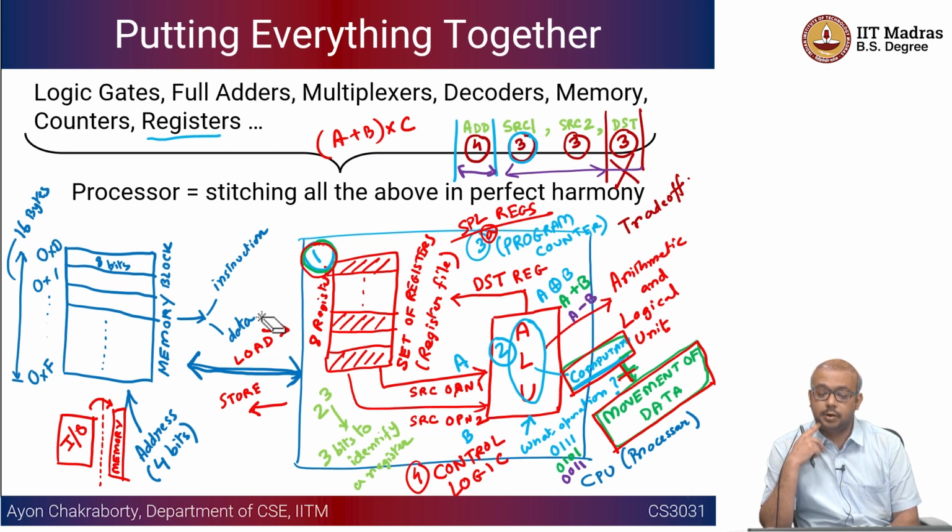But now note that you cannot execute these instructions in a random order. You have to first transfer the value of X to temp, and so on. Even if you change the sequence, your swap is not going to work. I gave this example because all of you are familiar with how the swap operation occurs. Similarly, for executing more complicated instructions where there are a lot of things to take care of, starting from register transfer to updating the program counter to doing the actual computation to writing back the results, they have very strict sequences in terms of time, which is taken care of by the control logic.